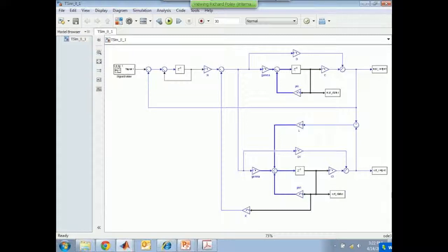Well, L, remember, fixes the eigenvalues here. So if you change L, your eigenvalues change. Yeah. I don't think that's going to work. Now, maybe there are other structures. Actually, there are many other structures of estimator. What I'm presenting here are linear state estimators. You can get a lot more inventive than this, but they tend to be non-linear and time varying and things like that. And I'm not going into that detail here. I'm just thinking.